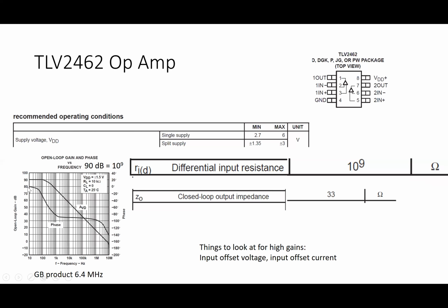The gain is plotted also in log units. Decibels are 10 times the logarithm to the base 10 of some ratio. So in other words, if you had a gain of 10, the logarithm of 10 is 1, because 10 to the power 1 is 10. 10 times 1 is 10. The gain would be 10 dB.